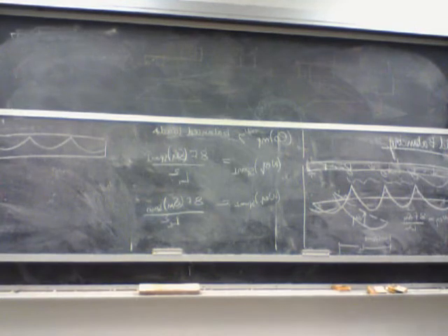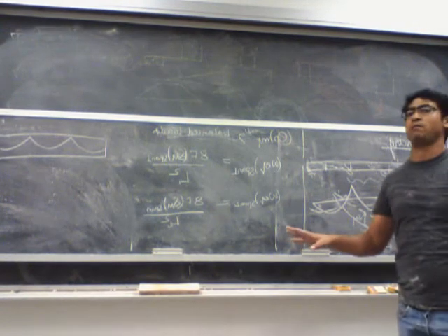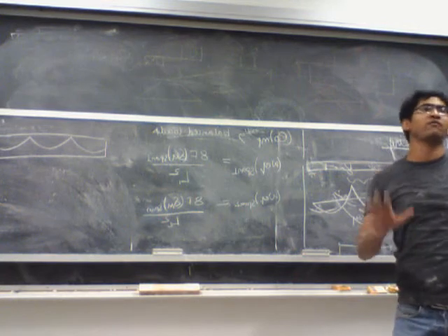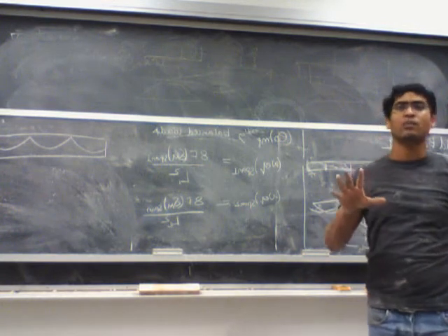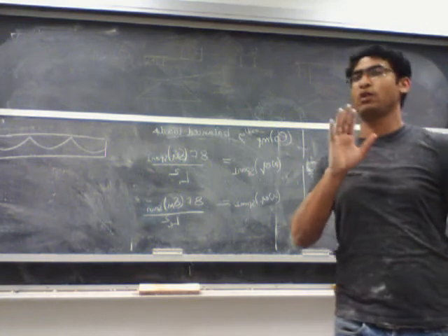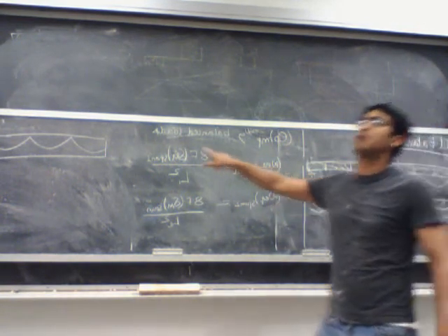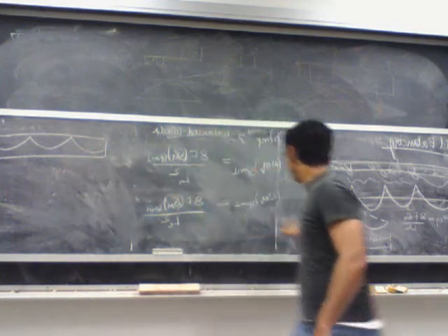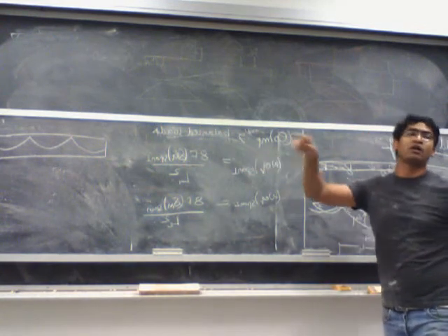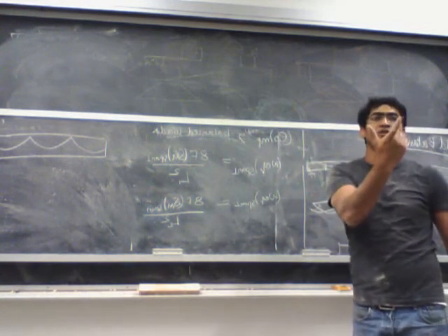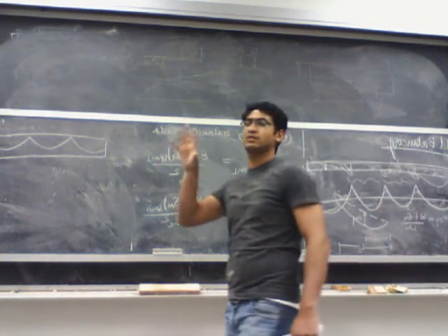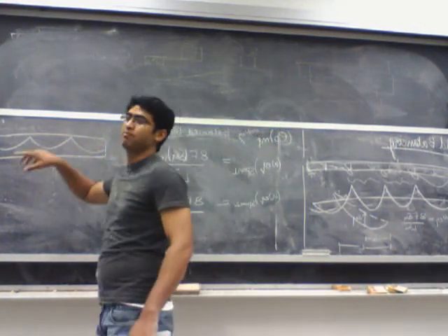So the only thing that you know is the tendon profile looks similar to the moment profile. It's not the same as the moment profile. It's not a scaled version of the moment profile. It just looks like a moment profile. That simply means that, okay, if this is a parabola, the tendon will also be a parabola. If the moment profile is a straight line, your tendon profile will also be a straight line for that particular region. That's it. It's not a scaled version, it's not anything, it just gives you the shape.